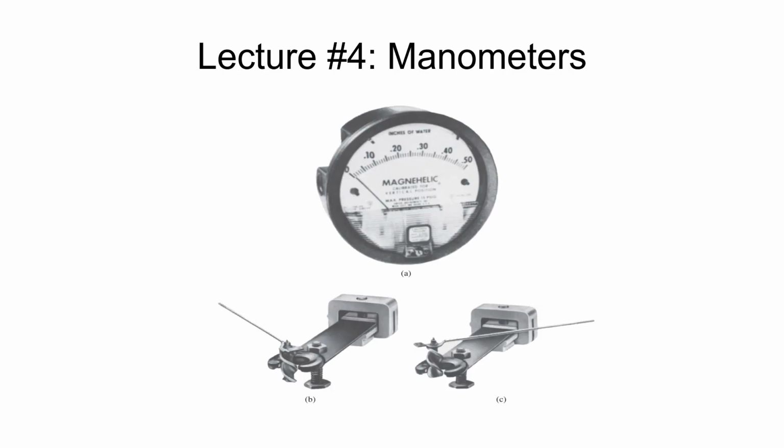Another one is a magnehelic type gauge. You see these a lot on different air handling units and HVAC equipment. This one moves the pin not like the burden tube does with the linkage, but instead it moves a magnet either closer to or further away from a coil that's attached to the indicator pin. As that magnet moves, the magnetic field changes, and it causes that spiral to rotate, and then causes the indicator pin to move and display the pressure for the device.